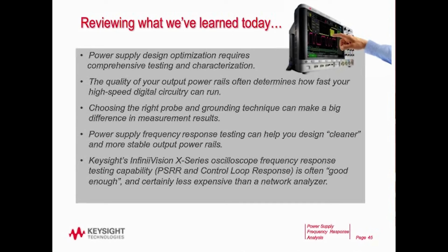Choosing the right probe and grounding techniques can make a big difference in the measurement results. The power supply frequency response testing can help you design cleaner and more stable outputs. And Keysight's InfiniVision X-Series scope with the frequency response testing capability is often good enough and certainly a lot less expensive than a network analyzer.